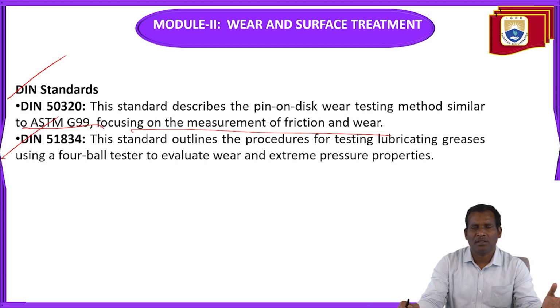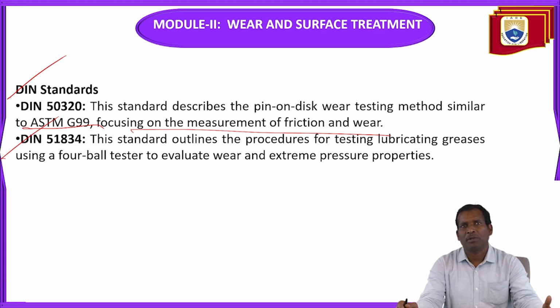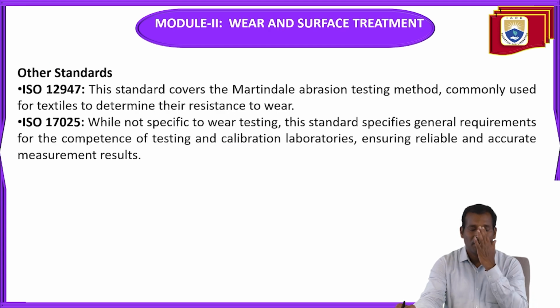DIN 50320 describes the pin-on-disc wear testing method. We have studied it in previous sessions. This method is similar to ASTM G99, and this standard focuses on friction and wear. DIN 51834 focuses on testing lubricating greases using a 4-ball tester to evaluate wear and extreme pressure properties.